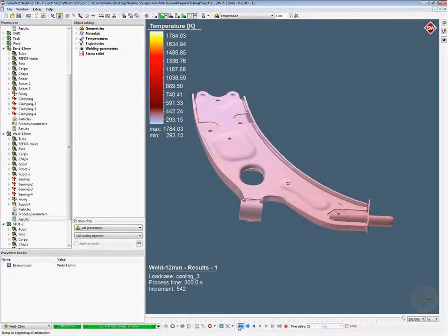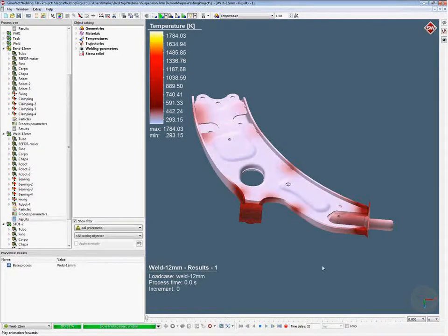And this is what they got after this. So after pre-bending, they weld again along this part. And it's only with one robot, because in the meantime they also found out that using two robots is too much heat input at the same time. So there is only one robot.